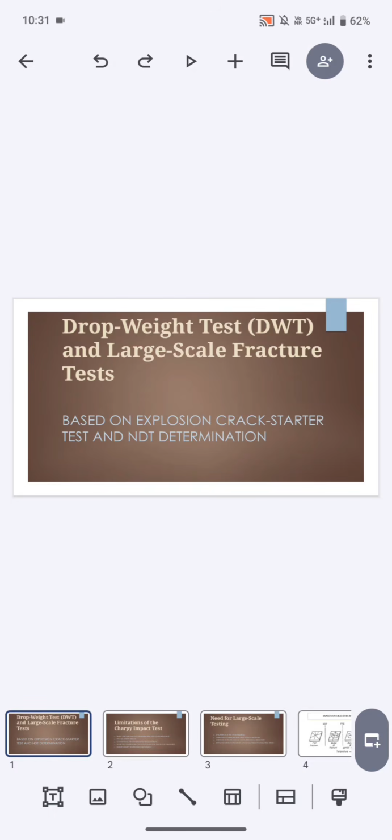Above the nil ductility temperature, a plastic bulge forms in the center of the plate, but the fracture is still a flat elastic fracture out to the plate edge. At still higher temperature, the elastic fracture does not propagate outside the bulged region. The temperature at which elastic fractures no longer propagate to the edge of the plate is called the fracture transition elastic, FTE.